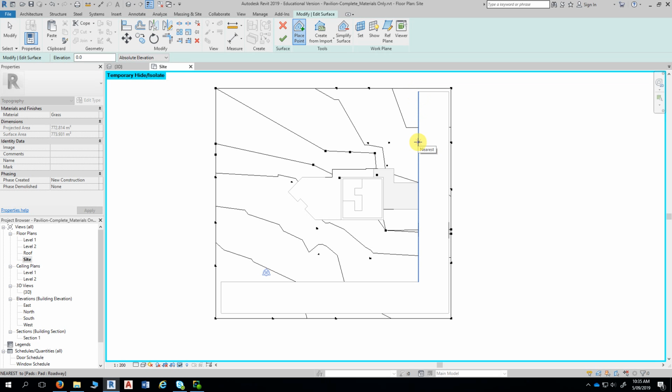And the aim here is to add points for the purpose of picking the terrain up so it meets the roadway, or drops just below the surface of the road. So where it's lower, it does this curve up to the roadway itself. And you'd have to work out the relationship between the topography and the pad or the roadway itself, work out your heights and so forth. So it just takes a bit of experimentation.